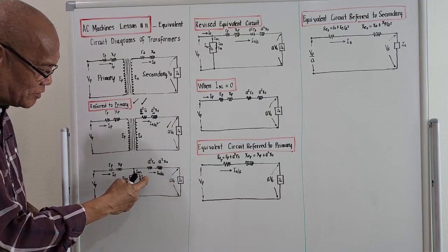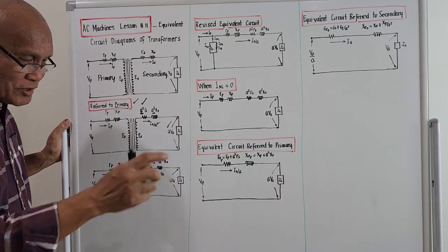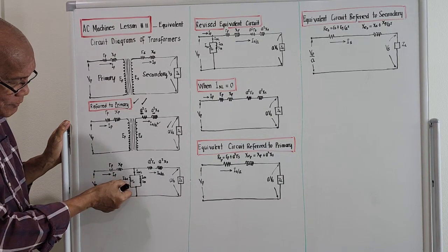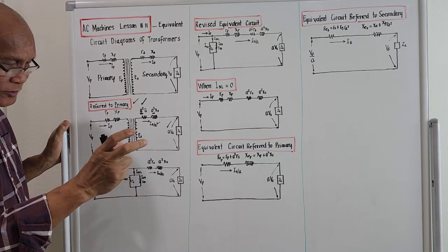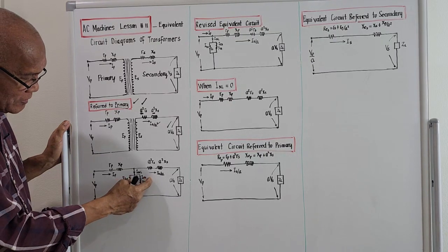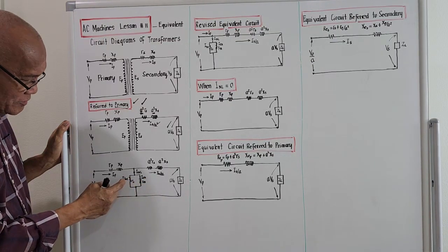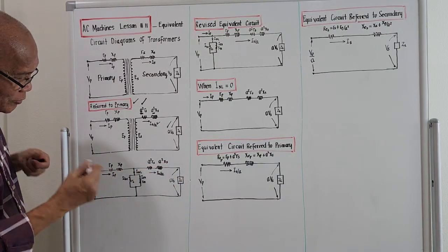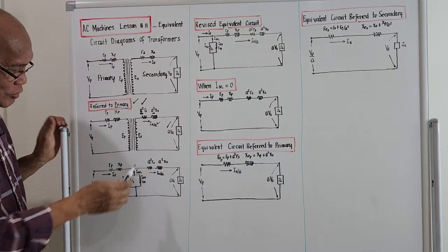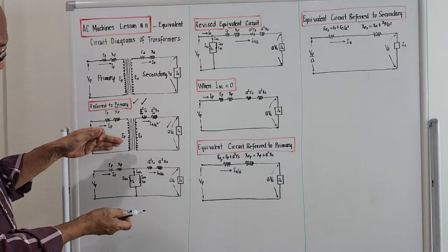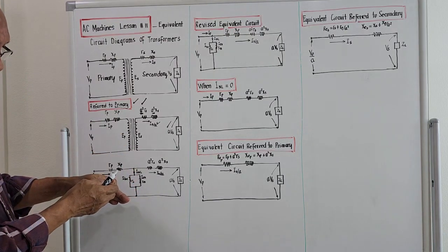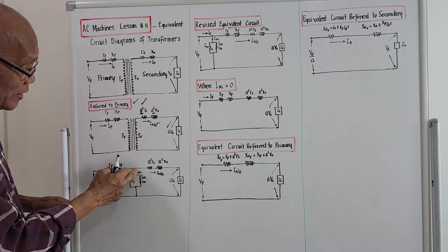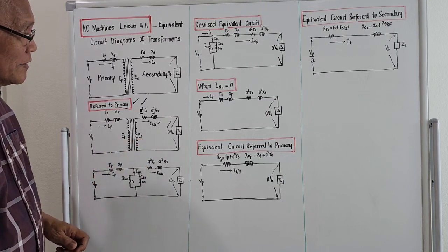The other loss is the hysteresis and eddy current, capital letter I with the subscript HE. So the vectorial sum of the excitation current plus the hysteresis and eddy current loss due to the lamination is referred to as the no load current. So we have a circuit at the middle consuming a no load current, designated as I sub N sub L.